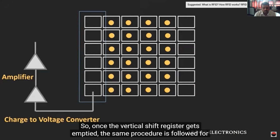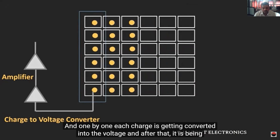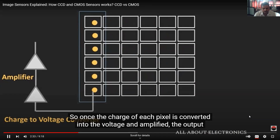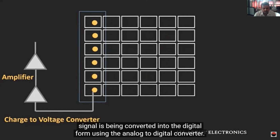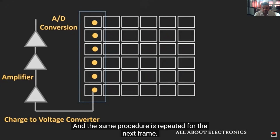Once the vertical shift register gets emptied, the same procedure is followed for the remaining charge, and one by one, each charge is converted into voltage, and after that, it is amplified. Once the charge of each pixel is converted into voltage and amplified, the output signal is converted into digital form using the analog to digital converter. In this way, one by one, the charge of each pixel is converted into voltage. The same procedure is repeated for the next frame. So this is the basic principle of the charge coupled device.